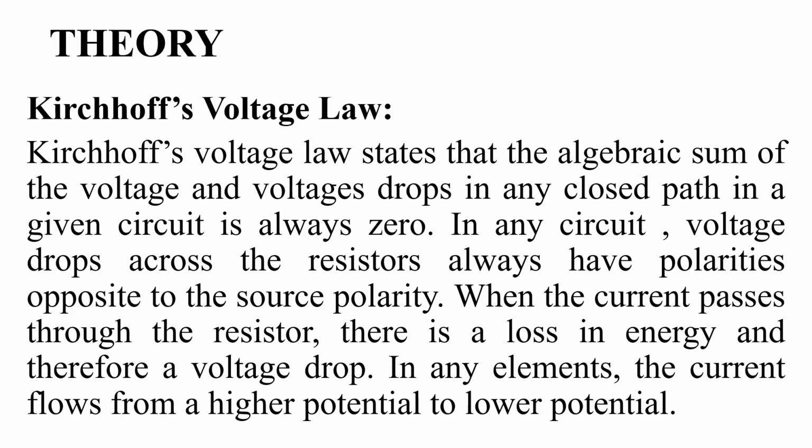Kirchhoff voltage law states that the algebraic sum of voltages around any closed path in a given circuit is always 0. In any circuit, the voltage drop across the resistor always has polarity opposite to the source polarity. When the current passes through the resistor, there is a loss in energy and therefore a voltage drop. In any element, the current flows from higher potential to lower potential.